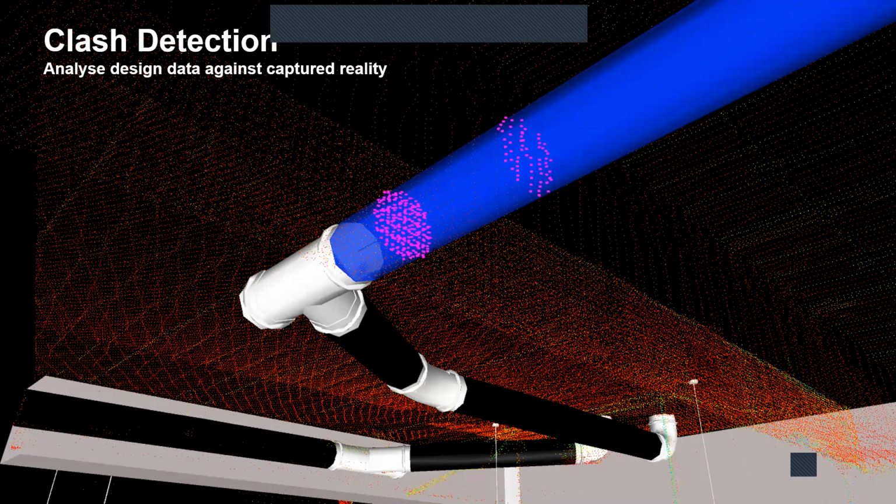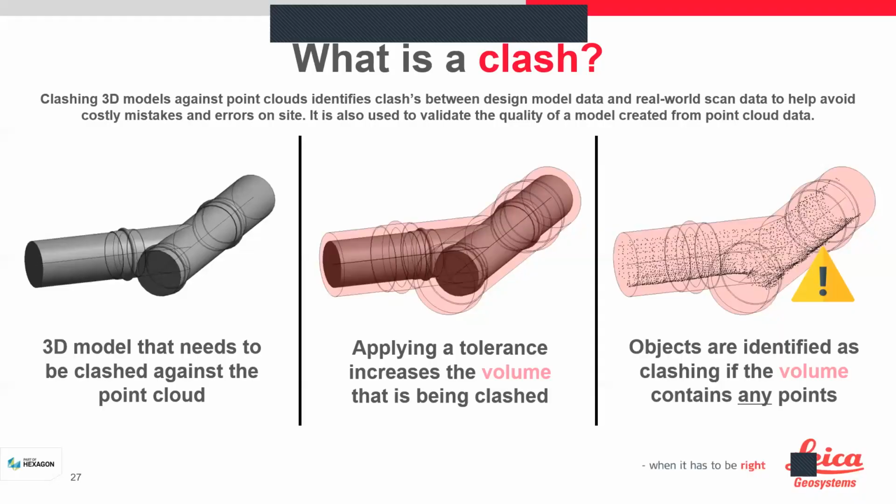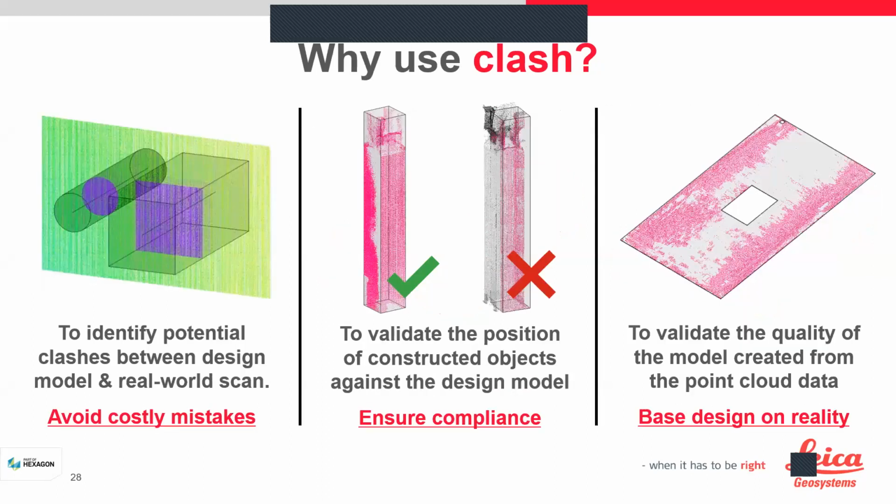In the same way, there are a few things where people make changes. The subcontractor for the HVAC makes changes and doesn't tell the BIM design person. So those are always unmeasured. In all those cases, if there is a clash, this solution can help us understand what the clash is and where it is, and this clash can be between the 3D model and the point cloud. It can be within the tolerance, it can be higher than the tolerance value, or it can be lower than the tolerance value. And anything which is higher or lower will have an impact on the building efficiency. So it can help in identifying the clashes before they happen.